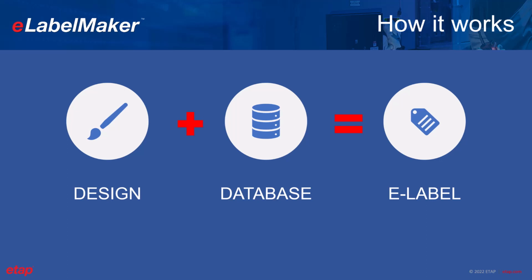You will have the ability to create your own template, which is the design stage. You could draw your label and have your corresponding information, and you can combine it with a database that is provided by the ArcFlash analyzer. When you combine these two, you get your desired ArcFlash label depending upon several locations that have different incident energy